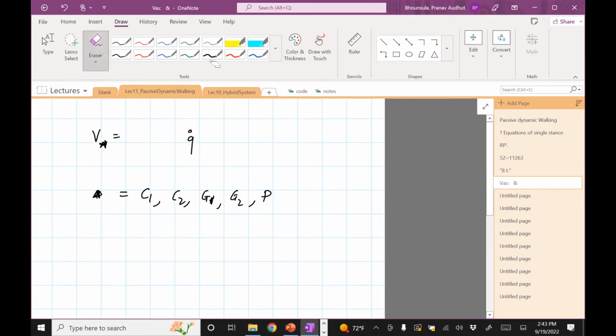My bad, this is wrong. I shouldn't write this. It should be J star, which should be d of whatever that point is, dq, times q dot, where this star is the Jacobian of that point. So it should be the Jacobian of the position vector, which we wrote down earlier, either C10 or G10, any of those. Of course, you take the x and y components only. There's x, y, and 1, right? Ignore that. You just take the x, y, and take the partial derivative.